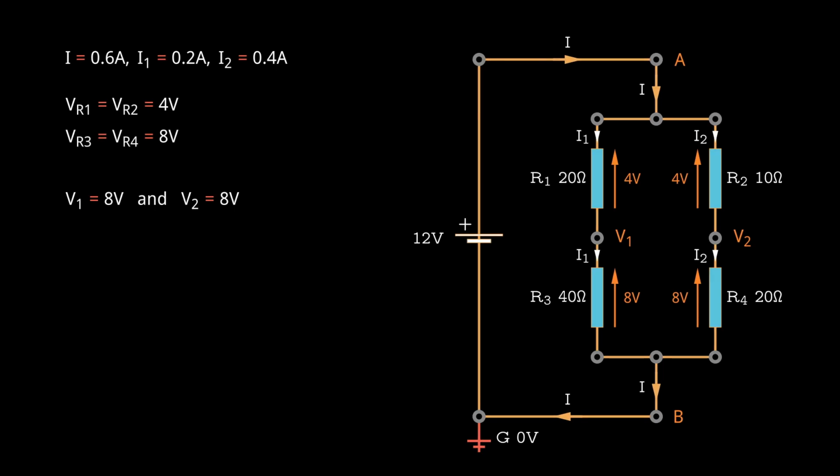What's important to understand is the advantage of identifying two nodes with equal voltages in a circuit. When two nodes have the same voltage, they are effectively at the same electrical potential, meaning there is no voltage difference between them. This insight allows us to simplify circuit diagrams without changing their fundamental behavior. By recognizing such nodes, we can make changes, such as combining or removing certain components between those nodes, which helps to simplify the analysis of complex circuits. Let's explore how this concept can be applied to streamline circuit analysis.